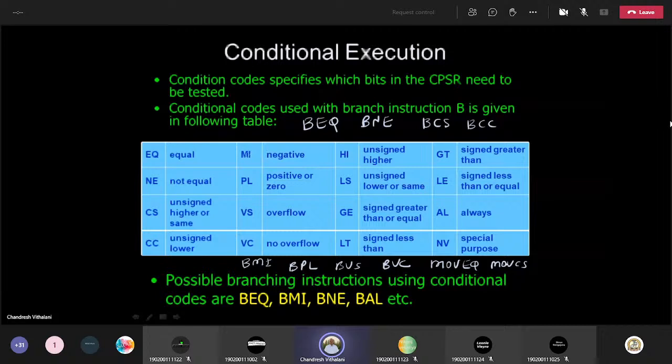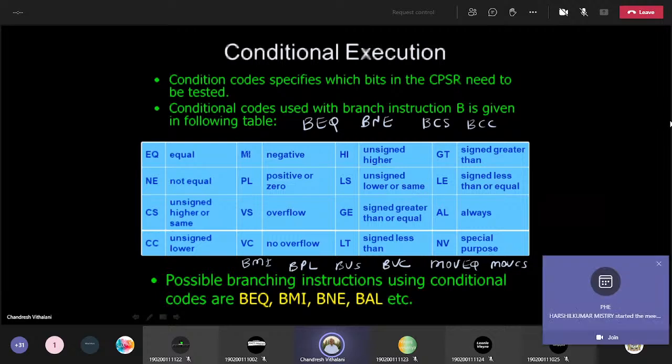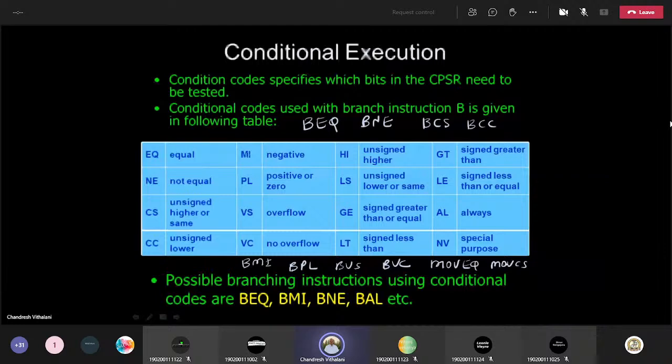But after execution, you came to know that this is a branch instruction. So now you don't want to run the instructions which are already there in the pipeline. Then you have to flush the pipeline. So if you use more branch instructions in your program, you require frequent pipeline flushing. And because of that, the throughput will reduce. So to prevent that, in ARM, condition codes are given. So if you use these condition codes wisely along with your assembly language instructions, then you will be able to reduce the number of branch operations, reduce the number of pipeline flushes, and increase the throughput of your program.